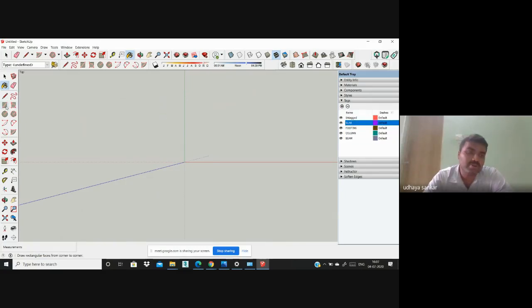Okay, now I'm going to take the rectangle tool, right? I draw the pedestal size. I simply draw 1.2 meter, comma, 1.2, that is 1.2 into 1.2, enter, right? Small size, right? Now we see automatically 1.2 meter into 1.2 meter. Simply go to dimension. You see this 1.2 meter into 1.2 meter. Our footing size will be created, right? 1.2 meter into 1.2 meter.